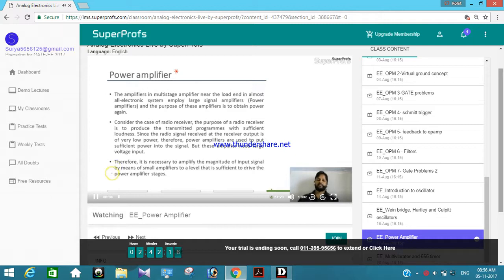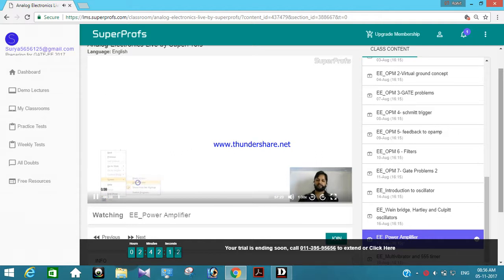So in the oscillator, again, if we'll discuss about the outcomes of all oscillators. First we have seen RC oscillator. In the oscillator, we have seen the frequency of oscillation is nothing but 1 over 2 pi RC root 6. We have seen the relation between RF and Rin, that is 29 R1. Okay friends, this was the first one.